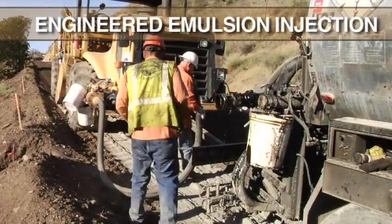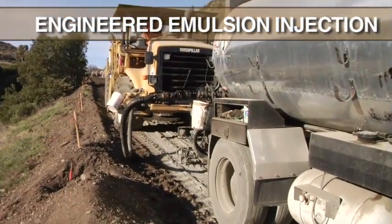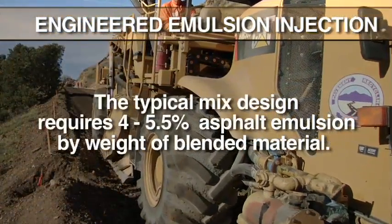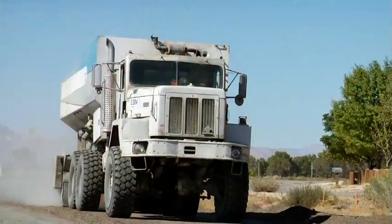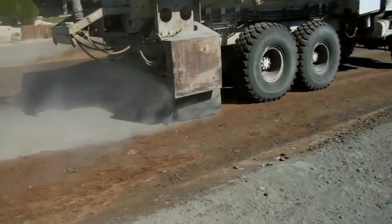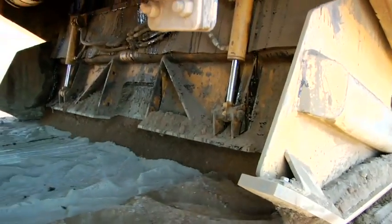Once the moisture content has been verified to meet the design limits, then the asphalt emulsion can be added. The reclaimer is connected to an emulsion tanker that injects the emulsion through a computerized rate-controlled metering system. The typical mix design requires 4 to 5.5% asphalt emulsion by weight of blended material. Here in California City, the mix design also required 1.5% Portland cement to be spread with a cement spreader prior to the addition of the asphalt emulsion. The cement was required to achieve the retained strength requirements of the mix design.